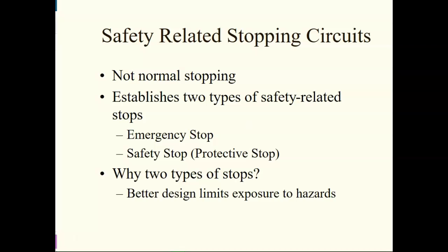So, safety regarding stopping circuits. We have a couple of different ways to stop a robot. We have the emergency stop, which would be done either with the dead man switch or hitting the giant red button. And we have a regular stop. Emergency stop, think slamming your brakes on so you can stop immediately because you're about to hit something. Versus a regular stop or safety stop, which is just going to come to its natural end, like you press on a brake pedal very gently and come to a gentle stop. That's what you actually want to do.